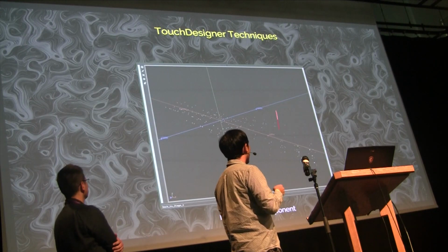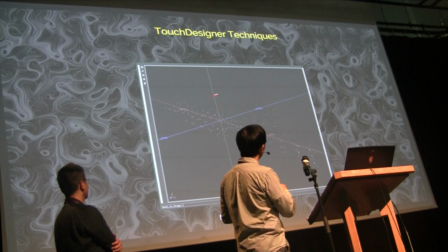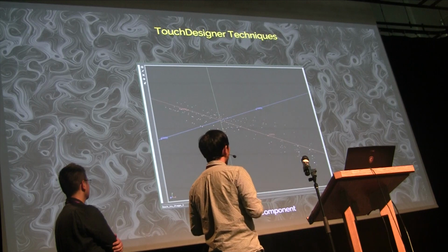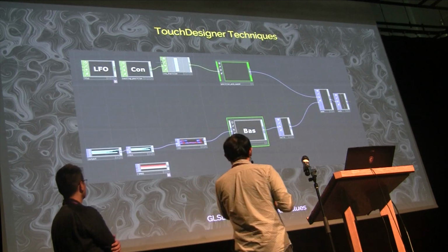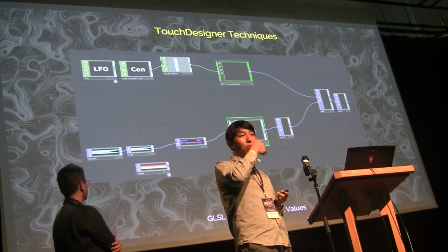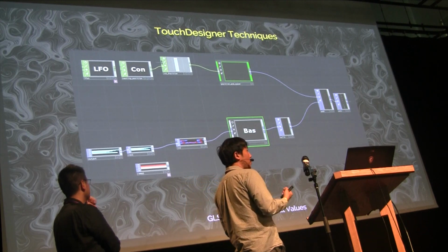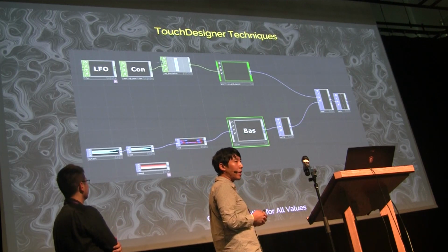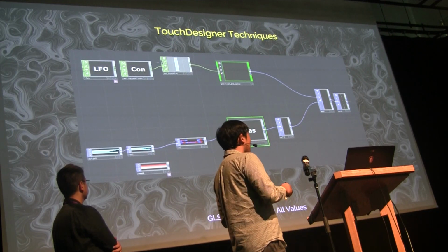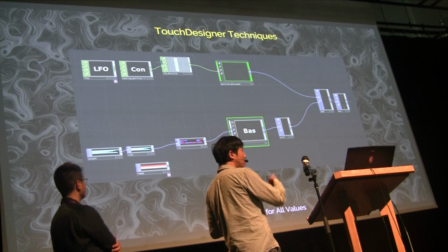So this is what it looks like when everything is imported to TouchDesigner from C4D. You see the small dots? That's the position of each kinetic light. And an interesting thing is we use GLSL to calculate everything because it's much faster. Even the movement is output as CHOP data. But in most cases the amount of data is too much.